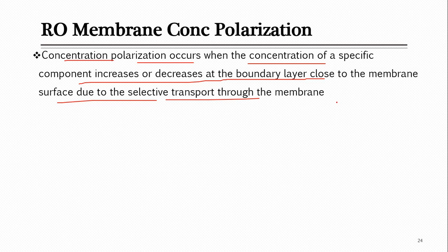As we know, we only allow, or we are looking for, solvent to pass through the membrane, so all salts will be rejected at the surface of the membrane. They start building up, and if they are not removed through the system, their concentration increases, and this phenomenon causes concentration polarization. And it is important, why?